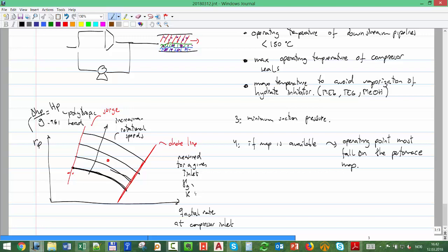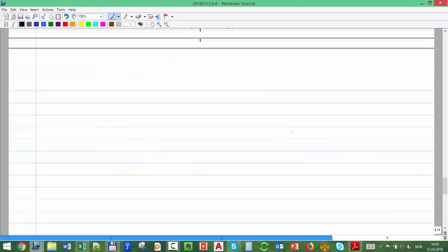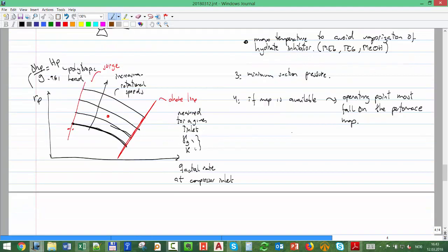Now, our compressor in our field will not be operating with air, right? We'll be operating with all kinds of gases that have different properties than air, and the inlet temperature will also change. So there is a way that I can change from this map at those particular conditions to a map for my particular conditions. So let me take a copy of that.